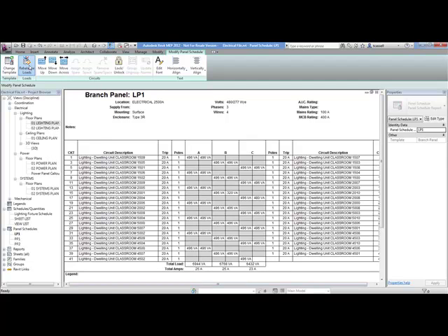What rebalance loads will do is it will take your panel and do the best it can to reshuffle your circuits around and make sure that phase A, B, and C are as close as possible. Now, it shuffled them around, it just didn't change all that much because we're already pretty well balanced. But when it does that, it moves all your circuits where it sees fit. For example, the room we just did, it moved to circuit 1.